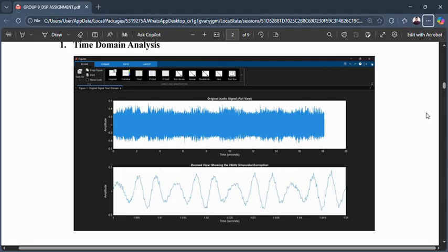So what is the effect on signal amplitude and quantization? You see that the frequency interference occupies a large portion of the amplitude range. So what we can understand is that this pushes the signal closer to the quantization limit. So this increases the risk of overlapping with each other. So the large amplitude sinusoidal noise pushes the signal closer to quantization limits. So this restricts the headroom for the original audio. So basically we cannot hear the audio from this.